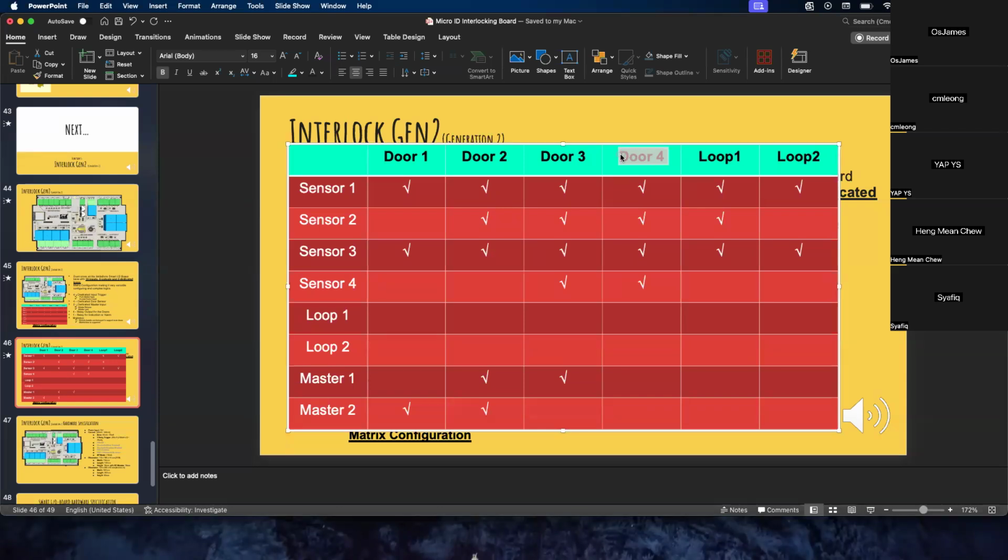So you can say that loop door 4 is the one shared by multiple loops. Then you can define that when door 4 opens, all the other loops should be locked. This is a bit technical, but if you have worked on interlocking or clean rooms, you get the idea of what is being said here.